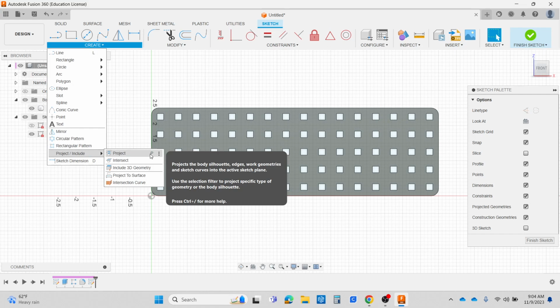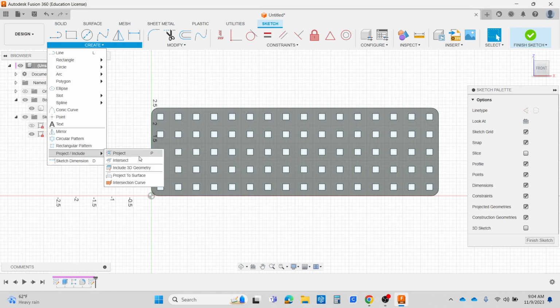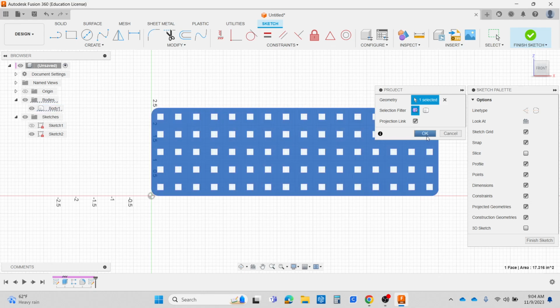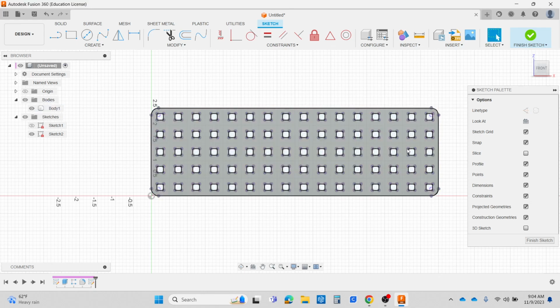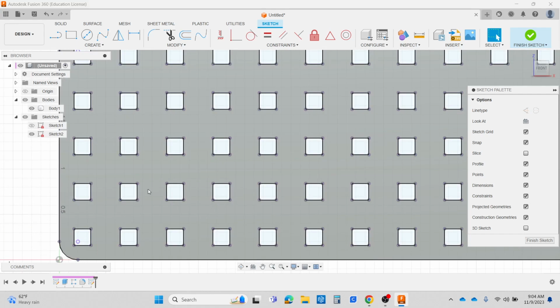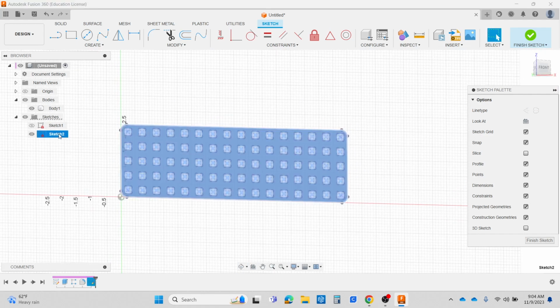Notice it has a P right here. So if you hit P on the keyboard, it's going to pull up a projection. You can go projection length. I can hit OK. And now I have the second sketch that's activated. See where the purple reference points are? So that one will actually name wing DXF. Wing DXF. And then I'll go save as DXF.